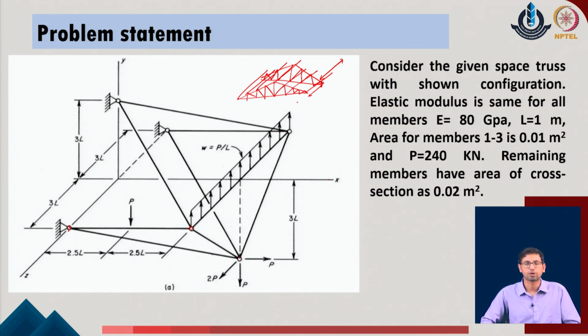Typically, to run these kinds of simulations in any standard software tool like STAAD Pro or ETABS, one needs to work out all the member orientations and everything. But as a very simplistic tool, one can easily generate one particular bay of the given system by defining the coordinates of the points, keep on generating the respective new bays by identifying the new coordinates with respect to movement of only another coordinate point, and easily provide this input to the given computer program and run this space truss for any given loading, right.